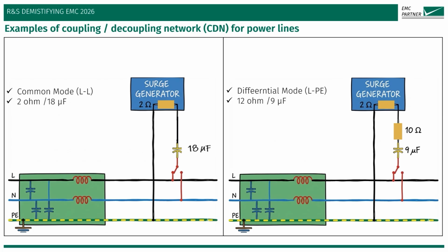The three-phase system expands to include L1, L2, and L3. This allows for complex testing between any two phases or from any phase to earth. These definitions ensure the precise, repeatable surge simulation required by the standard.